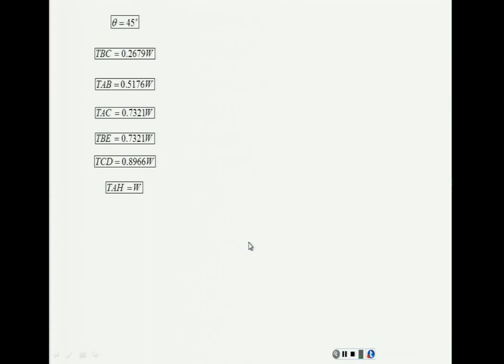But we also know what is the maximum value that those tensions can have. So I can start with this one and say 200 equal this times W, and calculate the W. 200 equal this times W, and calculate the W, and so on. And at the end, I have to select the minimum weight. Why the minimum weight? The minimum weight is going to be corresponding to the force or the tension that reaches its limit first.